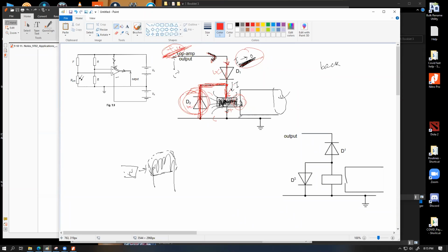Could you repeat that, sir? D1 will not oppose the downward current flow. The solenoid will produce the back EMF to maintain the current that it was energized by. So the solenoid will pull a downward current. If this alternate path does not exist, then the solenoid will pull the high current downwards. In that case, this is the only path through which the current flow can happen. Then D1 will allow all of that current flow because D1 will only restrict the current flow in the upward direction. Any amount of current flowing downwards, D1 can allow because it is forward biased for D1.